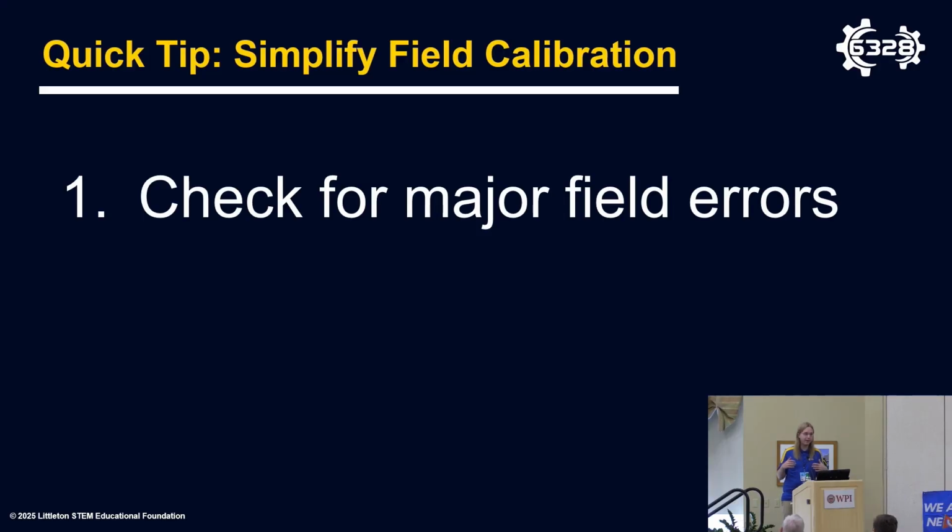Examples would include April tags that are simply in the wrong location, swapped with each other on the field, which we have caught before at our events. The robot was very confused when it saw those. We're more concerned about outright errors, not fields that are slightly out of tolerance. In general, trying to measure every field element or April tag location is rarely very useful, and really it's more a sign of a vision system that is not designed to properly cope with the natural variation in fields.